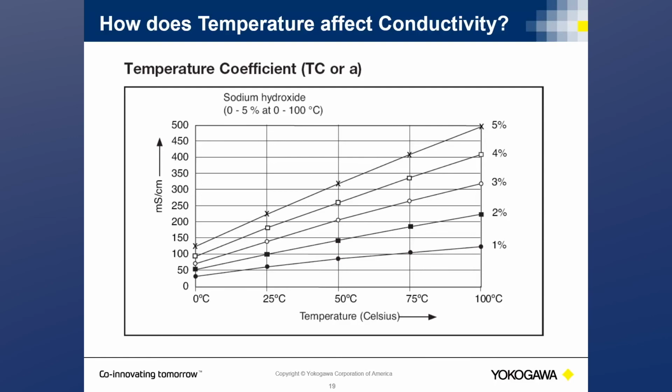However, in some applications like our brine manufacturing, which is commonly seen, the starting sample and the water that's being used to change the concentration have varying temperatures. Sometimes with the temperature electrodes, the built-in temperature element used for compensation is not quick enough to respond. Therefore, a change in conductivity reading is simply due to a change in the temperature that the sensor is actually seeing.